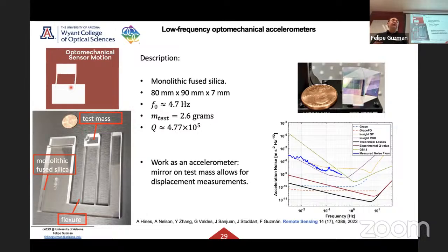And I guess the trick that we're pursuing is by selecting monolithic pieces of material and fabricating that structure from that monolithic piece. We're not fabricating the components individually and then gluing them together or attaching them together or welding them together. We're just etching out. Doing that, we basically inherit the properties of that material. Low mechanical losses are the key in this case.